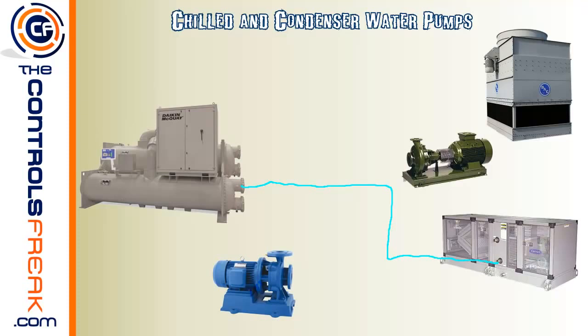Now we want to draw the water coming back out of the coil that's ready to go back to the central plant and get cooled down again. So that'll be this darker color here. And we'll send it this direction. And I'm sorry, pipes don't normally go on a diagonal slant like that, I promise. But it comes into the inlet of the pump. And in case you're not familiar with pumps, if you looked at this type of pump here, the inlet is actually going to be this horizontal part here. And there's an impeller in here, so you can imagine it like a boat propeller, but this is an impeller, which will actually draw the water into the center portion of it and then spin it around and shoot it out the top here. And this is going to go right back inside to the chiller.